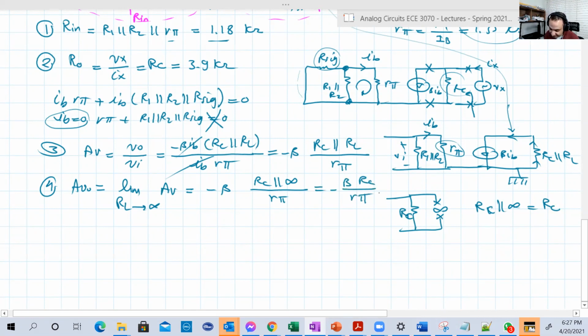Okay. And remember, these are the same expressions that we get from the first circuit that we explored. Exactly the same. I mean, the voltage divider circuit in AC analysis becomes just like one resistance between the base and the ground. Finally, number 5, GV. Of course, guys, for AV and AV naught, I'm showing you a new way to do it, pushing new ideas in your mind. If you want to do it in the same sequence, AV naught and AV, that's fine. You have many ways to get AV and AV naught.